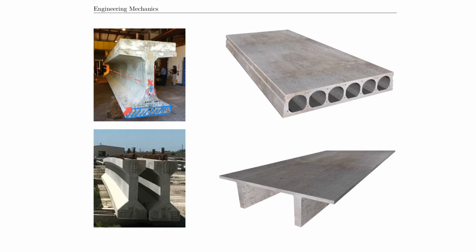But that is another reason why this beam is so wide here on the bottom, so that they can put a lot of pre-stressing steel in here. However, it is also a good reason to move a lot of material down away from the centroid, and it helps the engineer to really provide a lot of resistance. And by the way, in reverse, all this material here that has been removed from the cross-section would be very close to the centroid location, and therefore it wouldn't offer a lot of resistance to bending. And so that's why engineers build these beams like this.